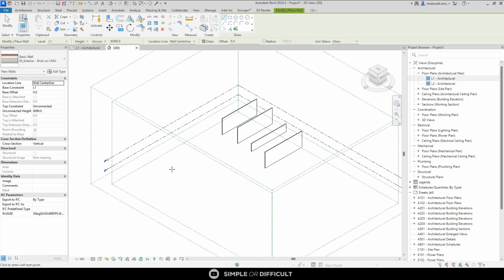So before I create this wall, I can use this to set the level where I want this wall to start. I can set L1 or L2. Okay. I can set the height, set it to height or depth. Okay, unconnected height is already this. So I can decide that, okay, I don't want the unconnected height to be that high. Rather, I can make it 2000 millimeters.